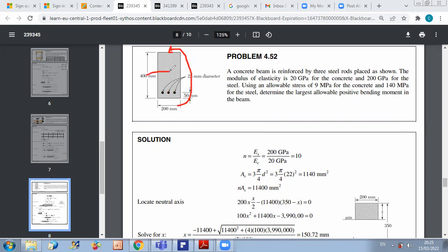So for the upper part, no need to do any change, because concrete can already sustain compression. However, because concrete is weak in tension, in order to not have rupture, we reinforce. This is what we call reinforcement. We reinforce concrete by using steel with it. And we consider that steel will support tension without relying on concrete.